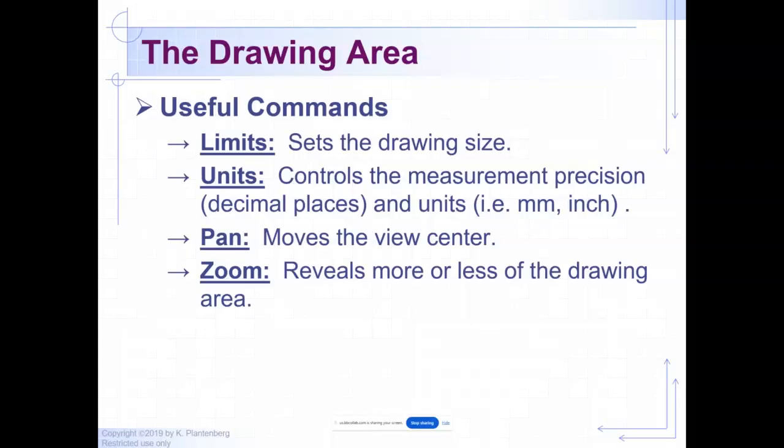And if I were to put them on a piece of paper and then scale them correctly, they would be the same size when I print them out physically on a piece of paper. But in reality, when I draw it in the computer, 1 unit is 1 unit in AutoCAD. It could be a millimeter, it can be an inch, it could be a mile if you want it to be, it could be a meter. AutoCAD doesn't care. Even though it says in there that you can set up using the wizard thing, you can set it up for millimeters or whatever. No, AutoCAD really doesn't do that.